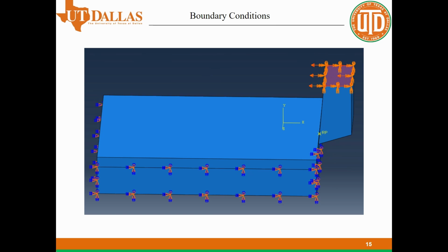For our boundary conditions, the bottom section of our base is encastered, leaving the top partitioned portion free to deform. The top of the tool is held fixed at the top face and moves 80 millimeters in 1 second. Note, this does mean it experiences an instantaneous acceleration, which prevented us from modeling faster cut speeds.